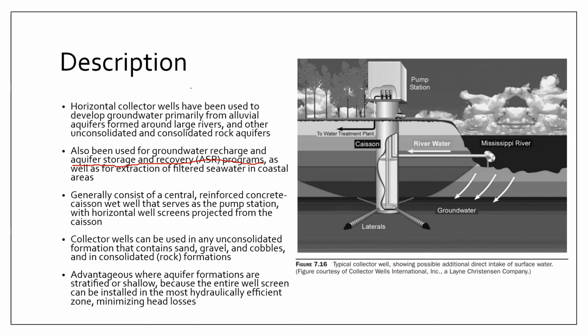All right, where in ASR you are artificially injecting water into your aquifer, so you will need a collector well that has a high capacity to inject a lot of water into your aquifer. All right, and collector wells are also used in coastal areas where you are actually using aquifers to filter out salt from your seawater.